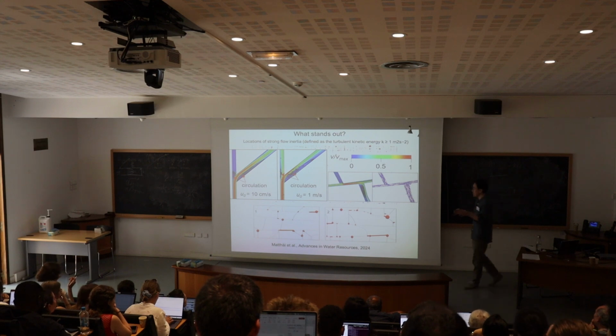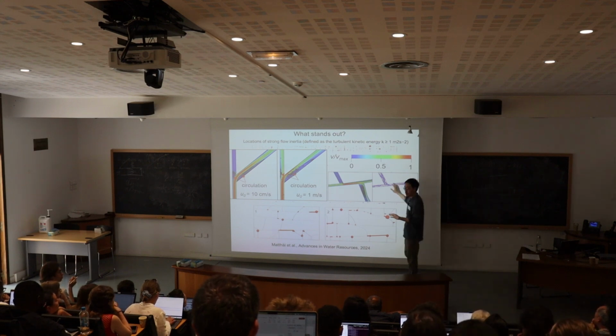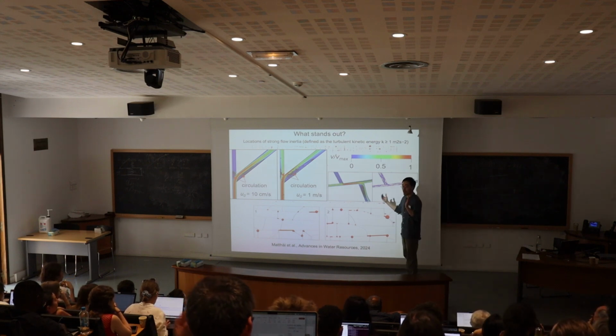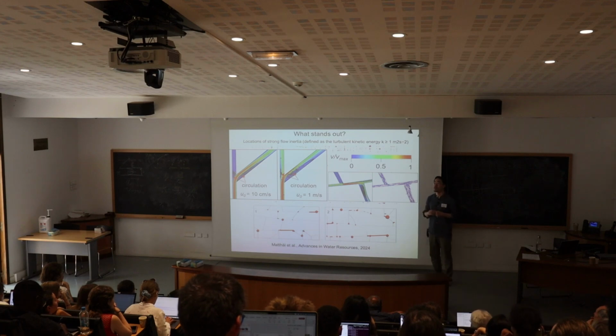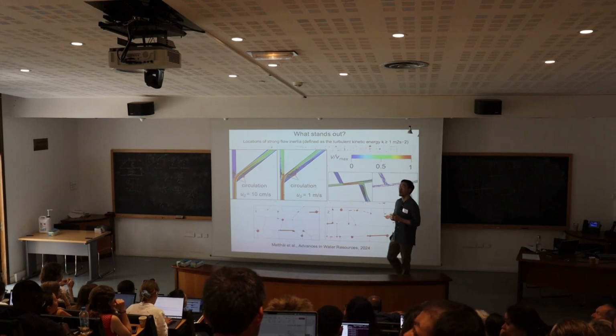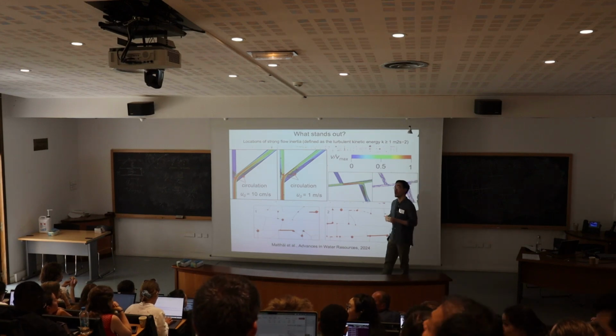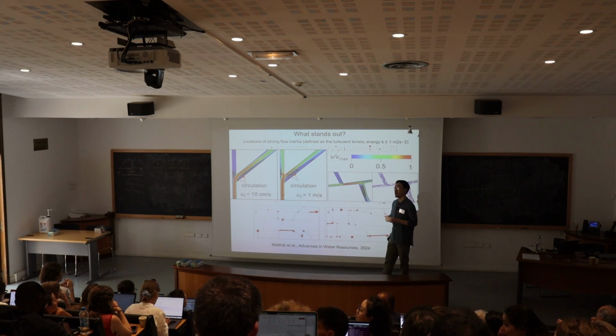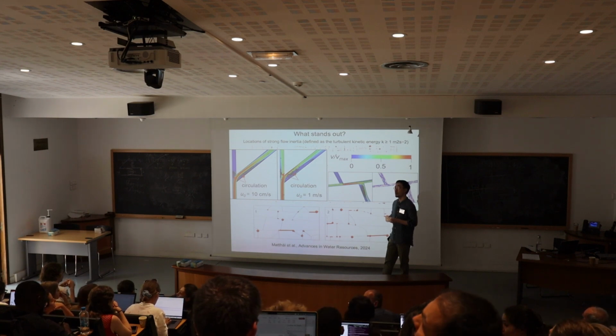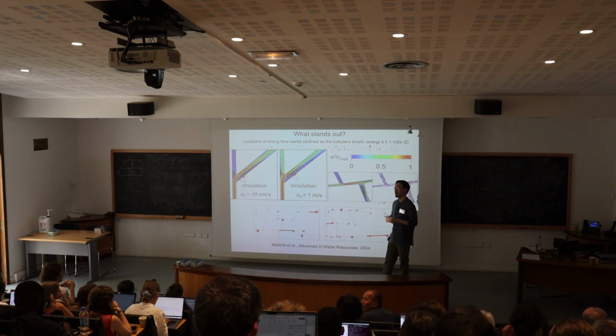And this will be the key message. This is not at all turbulence regime, this is inertia laminar regime. Yes? But what about the geometry? Sometimes, even for the same Reynolds number, if it's 2D, we don't see it, but if it's 3D and complex geometry, then you see these spirals. Right. Can you speak more about what's the role of the geometry in this?